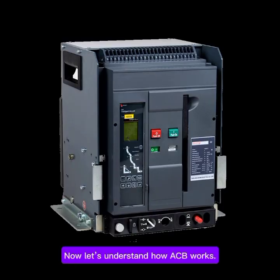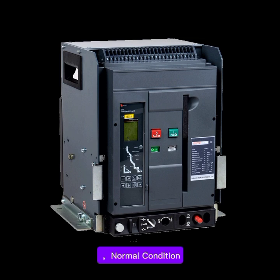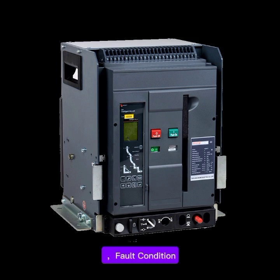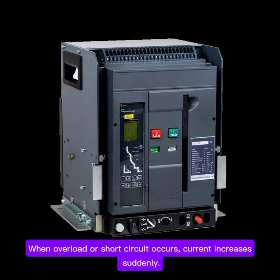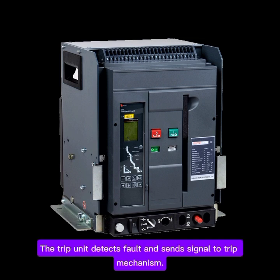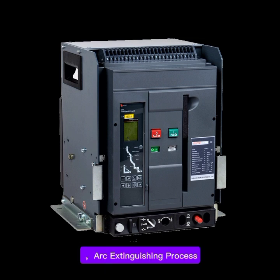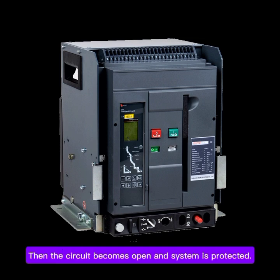Working principle of ACB. Now let's understand how ACB works. Normal condition. When current is normal, the breaker stays closed and supplies power. Fault condition. When overload or short circuit occurs, current increases suddenly. The trip unit detects fault and sends signal to trip mechanism. Then moving contact separates from fixed contact, and an arc is created. Arc extinguishing process. Arc moves into arc chute, where it is divided into small parts, cooled down by air, finally extinguished. Then the circuit becomes open and system is protected.